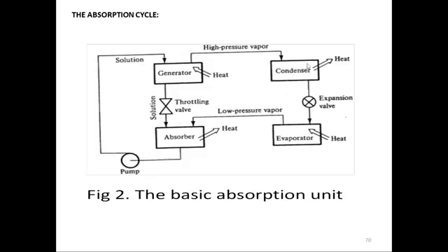which are similar to a condenser. One is the condenser process where the heat is being given out into the atmosphere, and this is the same condenser process as we had in the vapor compression refrigeration system. But this is for the refrigerant, and this one is for the solution. Here, the absorber is also acting similar to a condenser, but this is a condenser for the solution. So the heat will be rejected in the absorber also.